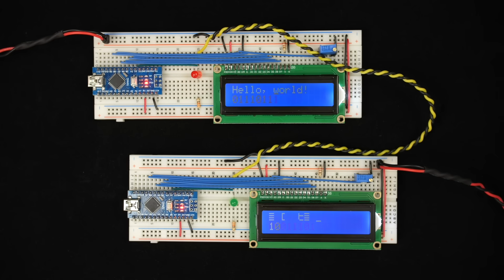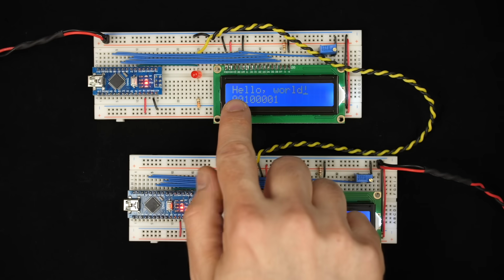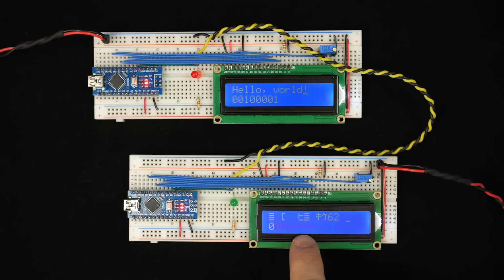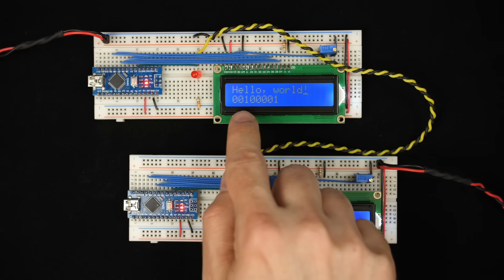Well, of course, what's happening is the transmitter is sending each character as 8 bits, and the receiver is receiving those 8 bits, but the 8 bits aren't necessarily lined up. That is to say, like the 8 bits that make up the H here that we sent, some of those bits might have been received partway through a byte here. And so those bits got shifted over. And so this first byte, which is this weird little character here, might have just been some of the bits at the end of the H.